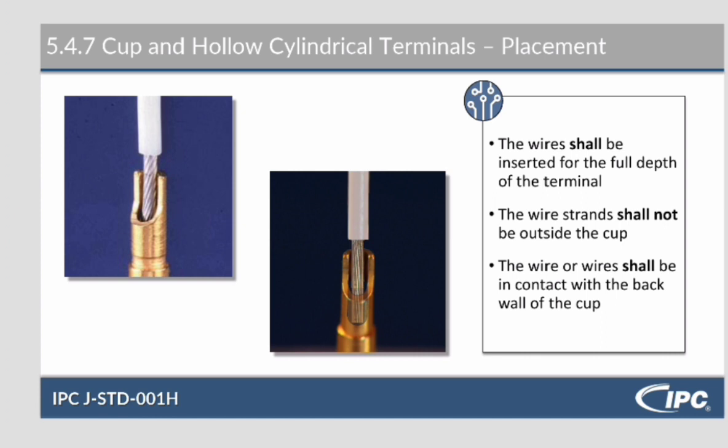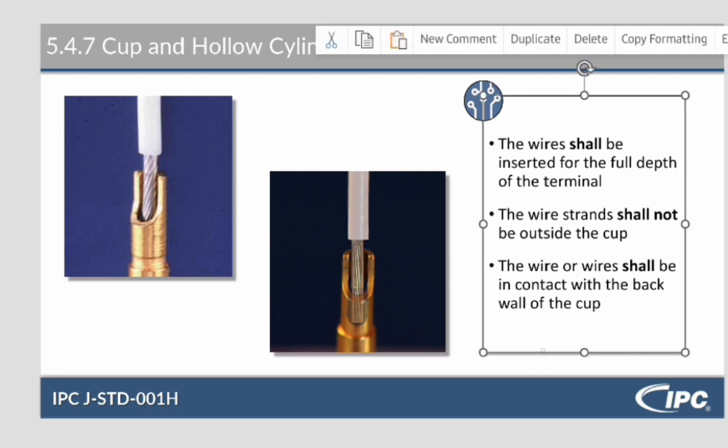So if you're soldering and you don't have your wire against the back of the cup, as long as you don't have strands poking out or it's falling off, it's actually not a defect. It's a process indicator. It's, this is okay this time, don't do it again. Knock it off. So yes, this bottom one right here, A1, P2, P3.